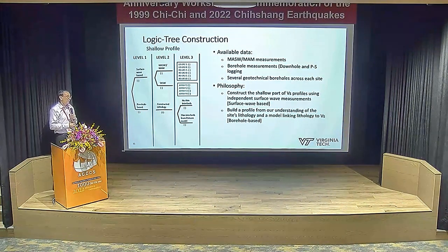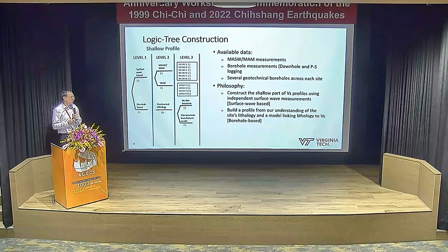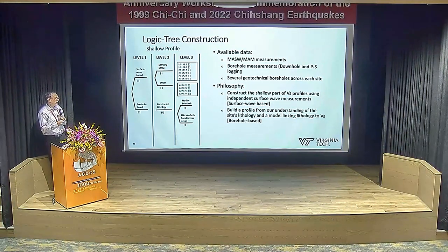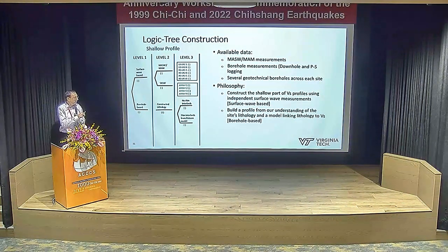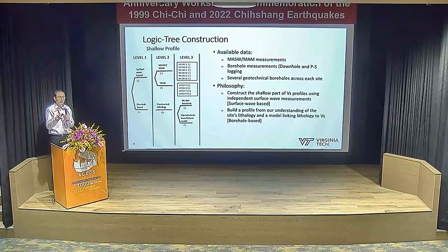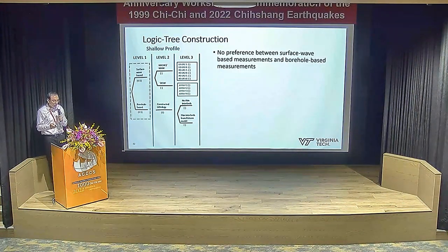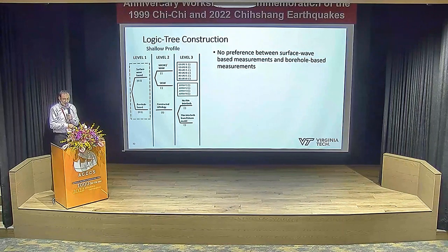Our philosophy in building the logic tree was to construct the shallow part of the VS profiles using independent surface wave measurements, and to build the profile from our understanding of the site's lithology and a model linking lithology to shear wave velocity, using measurements of velocity that were obtained from borehole-based measurements. So there was no preference given to surface wave-based measurements or borehole-based measurements.